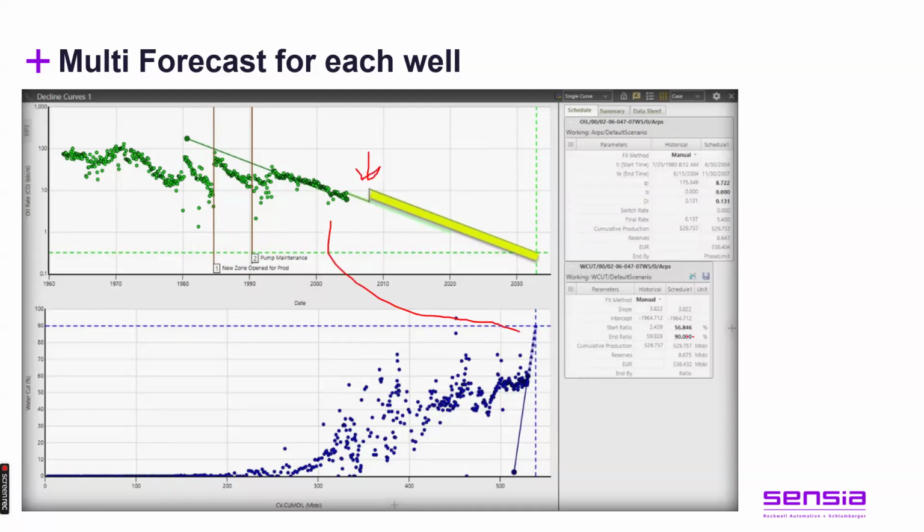You see, my water cut threshold is 90%. So OFM will stop here until you cannot produce anymore. You have to do a workover. Could be gas oil ratio, could be bubble point pressure, whatever, right? But it will ask you to do a do-nothing scenario, to tell you in this scenario, I cannot produce anymore. Not because I reached my economic rate, not because of a time limit, no, because you reached your reservoir constraint, which is water cut, or a facility constraint. Then what should I do? Then you design a workover. Okay, I will do the workover now here.